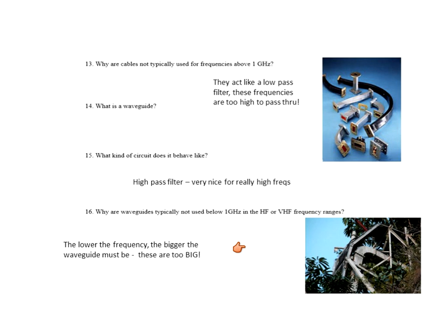It's really big. So why are waveguides not used below 1 gigahertz in the HF and VHF range? Well, it's because the waveguides become too large and too cumbersome. They call this the AB window here when you look at this rectangular side. The A side is the long side, and the B side is the short side. And the A dimension and the B dimension has a lot to do with the lower cutoff frequency. And the lower cutoff frequency is inversely related to the size.